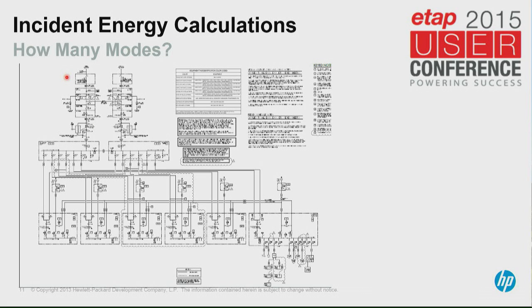But if you're looking at this system, we have two primary medium voltage feeds. We basically have medium voltage distribution with a tiebreaker between them. We have unit substations. Essentially, each unit substation can be fed from either medium voltage distribution side, either utility source. Each unit substation has its own dedicated generator. This is basically a block redundant topology. Then, to make matters more interesting, each of these 5 primary distribution systems has a UPS system and critical distribution.